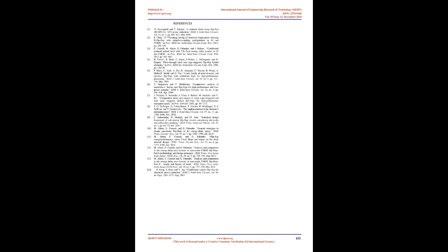5. Conclusion. Various pulse-triggered flip-flops were reviewed. A universal flip-flop with the best performance, lowest power consumption, and highest robustness against noise would be an ideal component to be included in cell libraries. The combination of a pulse generation circuitry and a latch results in a positive edge-triggered register.